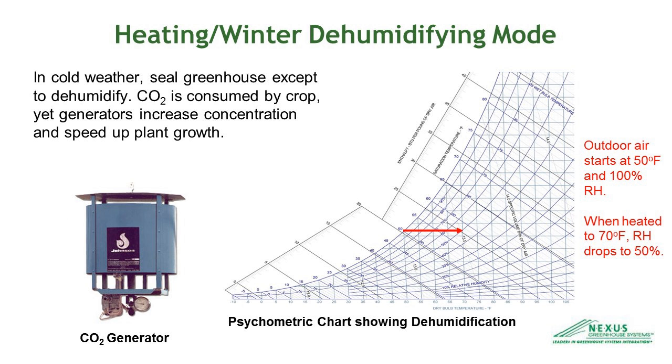And sometimes the choice of equipment depends on the climate. Oftentimes if you're in a hotter climate and you're not going to have much demand for heat, you wouldn't install a large centralized boiler system. You'd probably use unit heaters just to supplement the amount of heating that you need the worst time of the year. However, if you're in a very cold climate, you're going to most likely want a very efficient system like a centralized boiler because you're going to run that system a lot. The other thing with heating, keep in mind, is it's always good to have redundancy in case one of the systems fails.